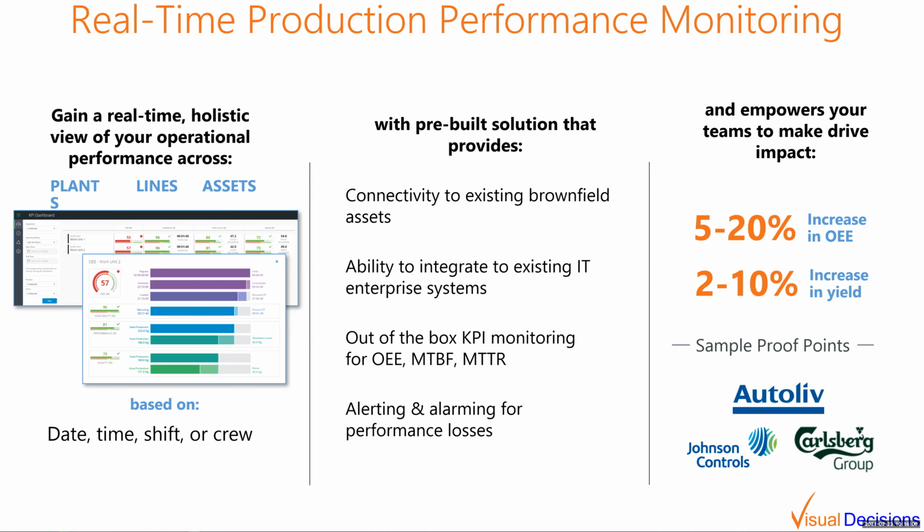I have customers that are doing statistical process control rules on those process variables coming off of the machine controller itself, so that they can see when things are essentially getting out of control, and utilize that for their condition-based maintenance. You can set it up so that it utilizes all of the Western Electric rules, whether it's 2 data points out of 3 outside of 2 sigma, any point outside of 3 sigma, etc.